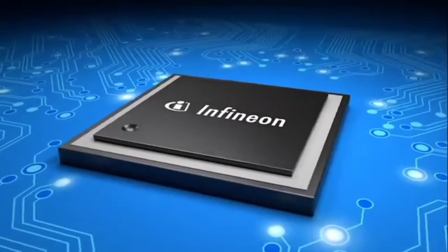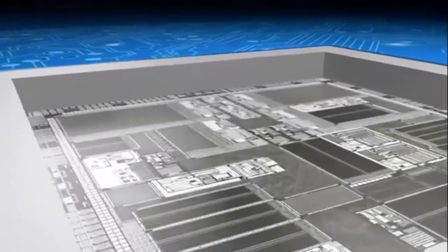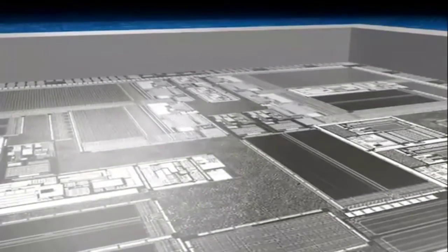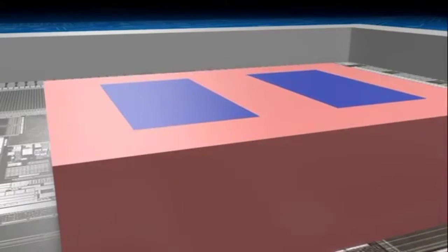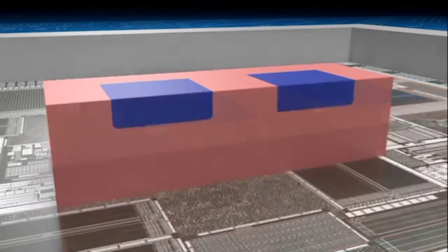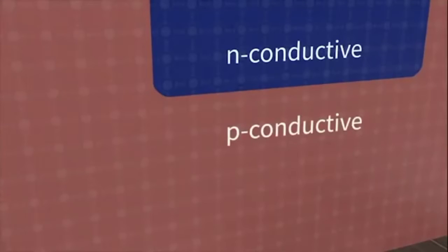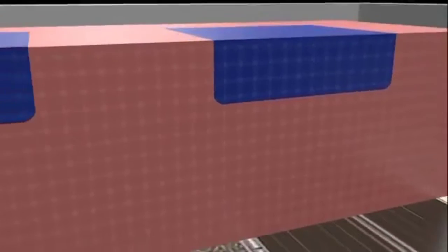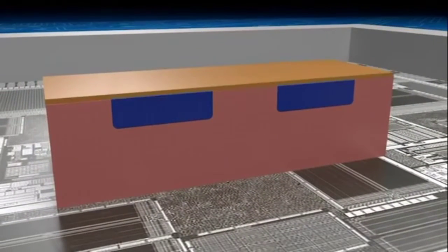Transistors are built on the p and n-conductive layers that exist in a doped wafer. Transistors are the smallest control units in microchips. Their job is to control electric voltages and currents, and they are by far the most important components of electronic circuits. Every transistor on a chip contains p and n conductive layers made of silicon crystals. They also have an additional layer of silicon oxide, which acts as an insulator. A layer of electrically conductive polysilicon is applied on top of this.